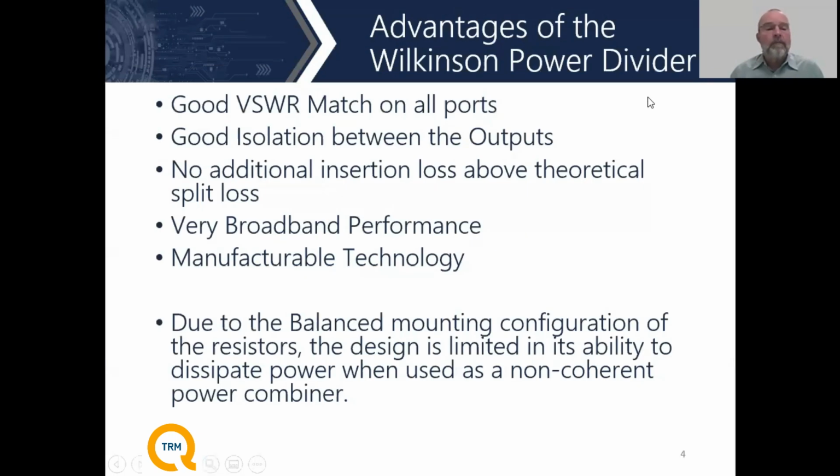Sure. So the Wilkinson, the way that we currently have it, has very good VSWR match on all ports. We have good isolation between the outputs. It is essentially a lossless device. We're basically just looking at ohmic loss of the copper right now, so it's very low loss. It can go for very, very broad bandwidths. You can easily achieve 10 to 1, 20 to 1 bandwidths using the current technology, which is octaves and octaves above the 20% bandwidth of the previous art.